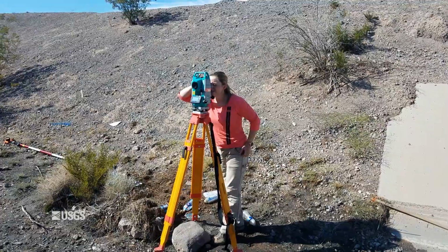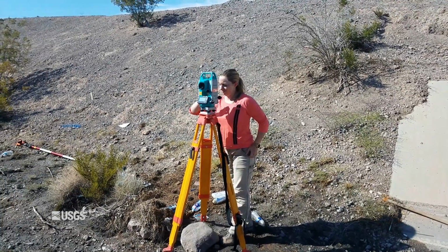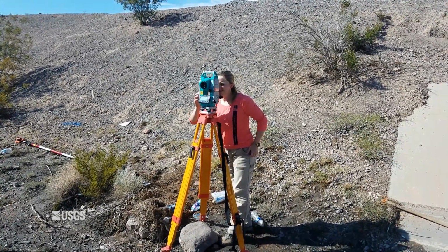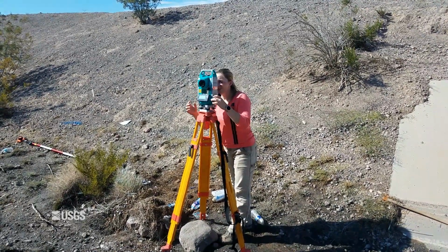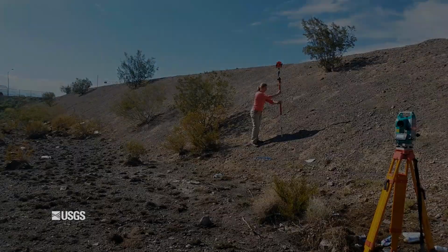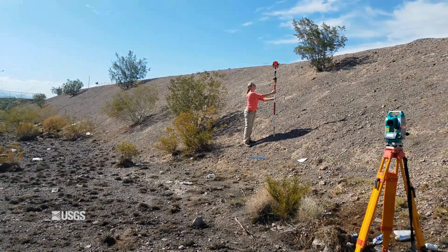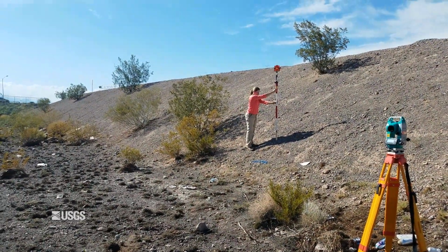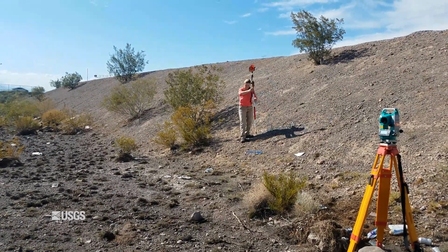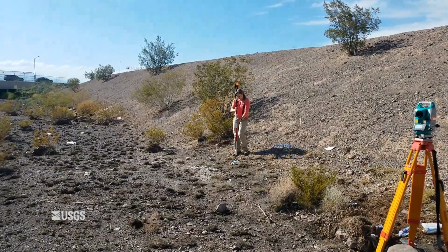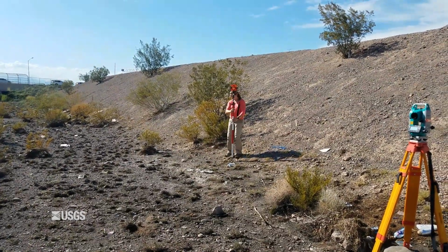There's no need to survey the high watermarks again because we already shot them, although you may want to search again for marks at or near the cross-sections you selected, especially at sections where none of the marks flagged initially were close. How many points should you choose for your cross-section survey? Well, it depends. Keep in mind that your entire measurement will be based on the area that you define from this single cross-section survey, so it will be in your best interest to make the survey relatively detailed.